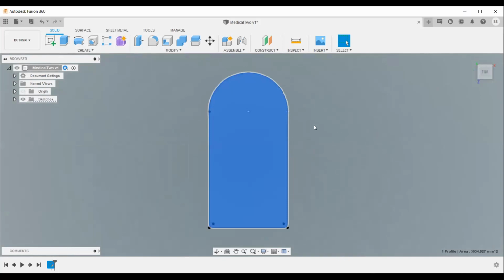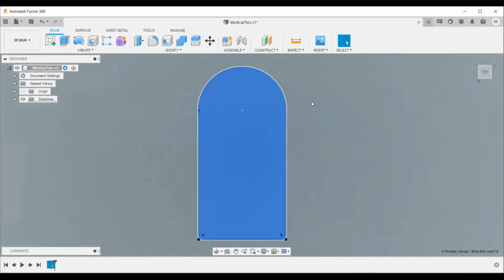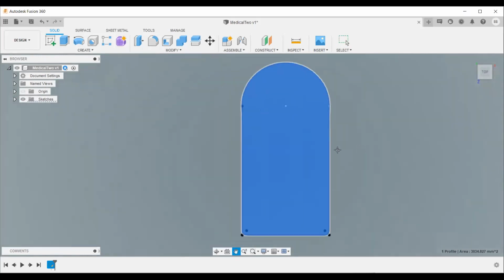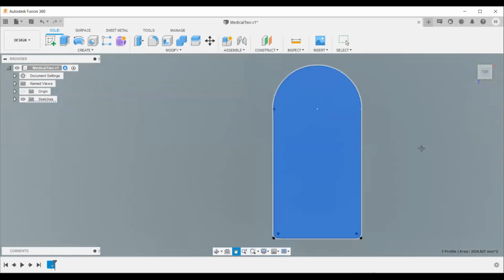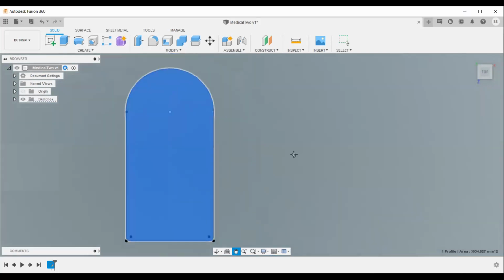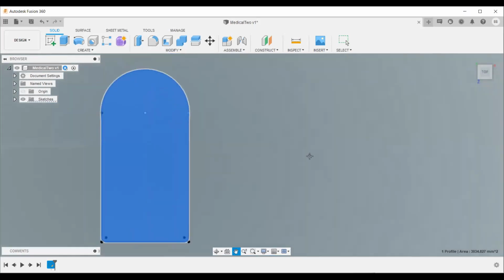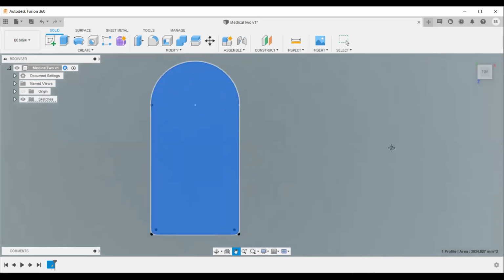And then I want to just highlight some few things to make your work easier in the software. To rotate your part, you have to long press the scroll wheel, then you can move it left, right. You'll be able to pan, to move your drawing left, right.